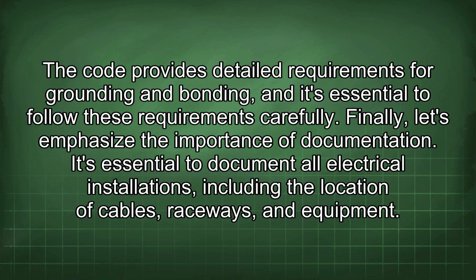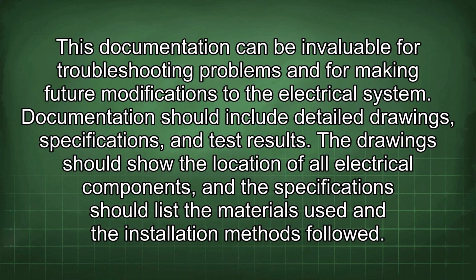Finally, let's emphasize the importance of documentation. It's essential to document all electrical installations, including the location of cables, raceways, and equipment. This documentation can be invaluable for troubleshooting problems and for making future modifications to the electrical system. Documentation should include detailed drawings, specifications, and test results.